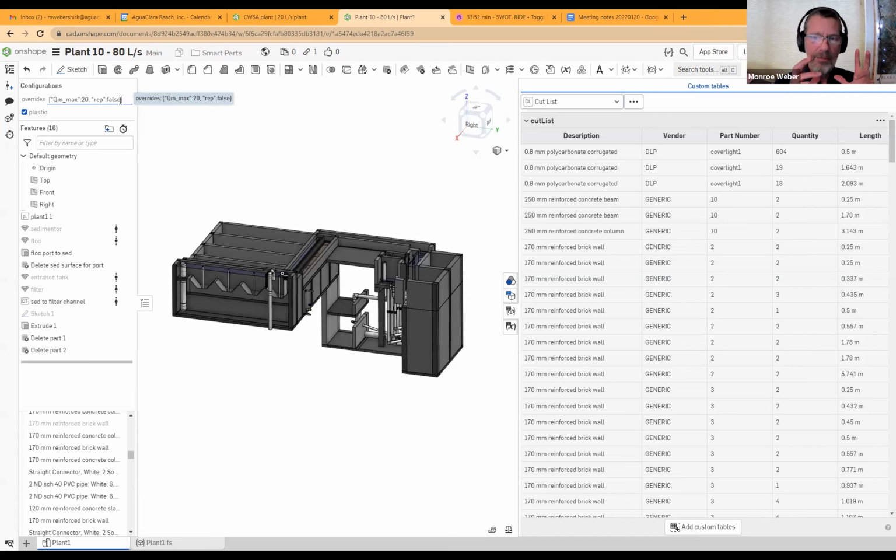And you might be wondering, given that everything can change in dimension, and yet even when it changes in dimension, things remain at the right relative positions to each other. The way that we've done that is by placing the mate connectors on the parts in stable locations where it then makes sense to always have the other unit process be attached relative to that location. I feel like I didn't answer that question, but you will play with mate connectors and bringing parts in your next assignment.